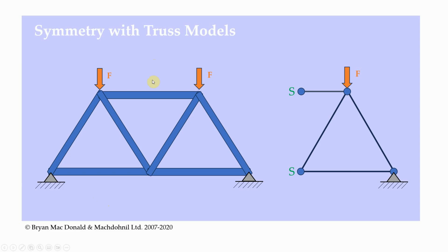So if we were to draw a line down to the middle of this bridge structure and simply mirror one side over, we'd get the full structure. In this case, our finite element model of this bridge is going to look something like this. We're going to use 4 truss elements: one here at the top, one here, and one here. We fix this point here, we put a load on this point here, and we're going to define a symmetry edge on these points here. In other words, we're going to tell this model that it's reflected about these points, in the horizontal direction, which is very important.